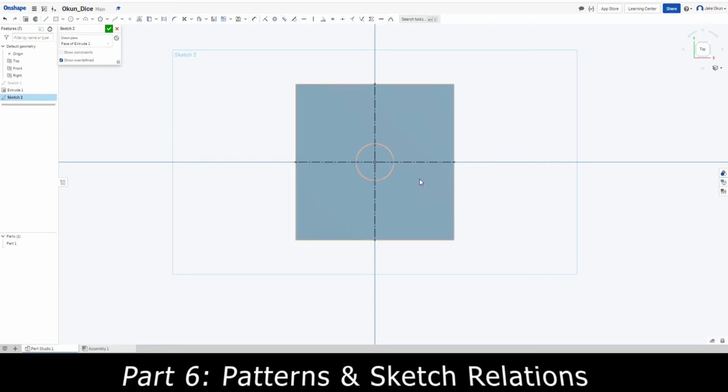So this one's perfect. The only thing that's left is we're going to have to dimension out our circle. For each of these circles, I'm going to be very careful and make each of them 0.025 inches on all sides, regardless of the size of the specific one. So now we have that over there, and then we're actually going to change it. This does look a little small, so I will make this one 0.1 inches. And then from there, we can extrude it.